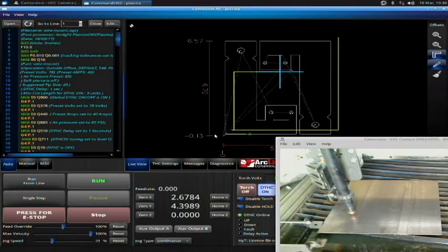So generally the machine, if you keep your standard settings in SheetCam, you will cut the interior cuts first, and then the exterior cut of a part, and then it will move on to the next part. I'm just going to clear this line to kind of make this a little easier to see.